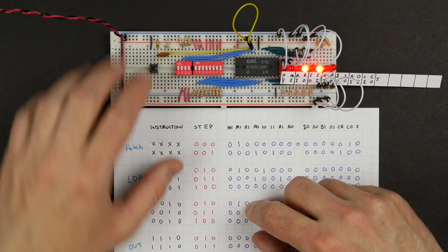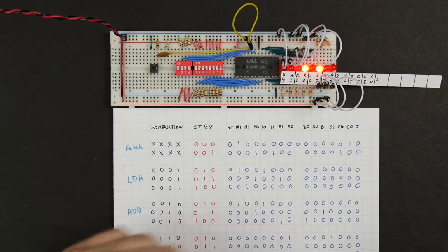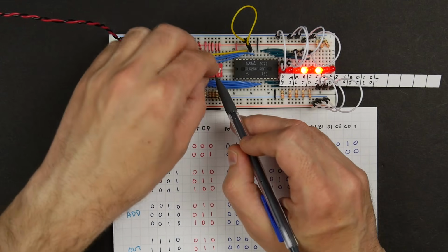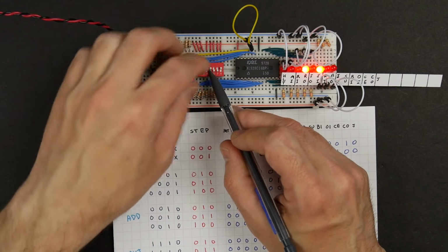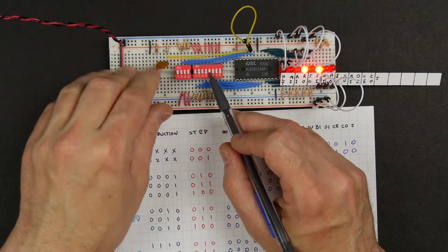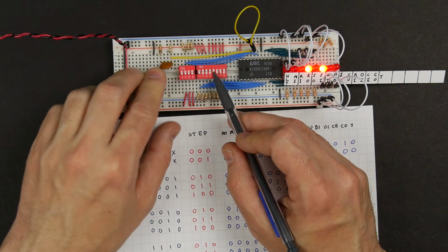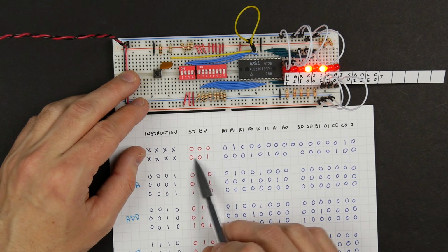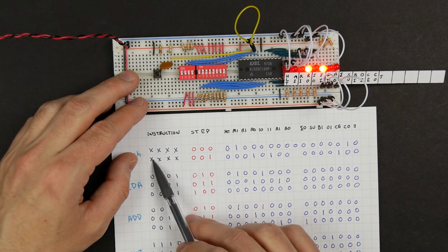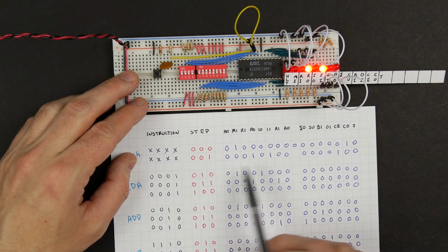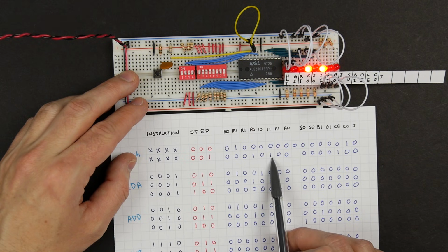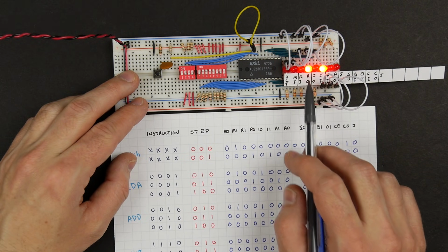Again, any instruction. So I'll set that for instruction 0, and then I'll just cycle through the remaining 15 instructions and set it for each of them, just like we did with the last step. Okay, so now for step 1, all 16 instructions, any combination of instruction bits, we've now set this RAM out, instruction register in, like that.